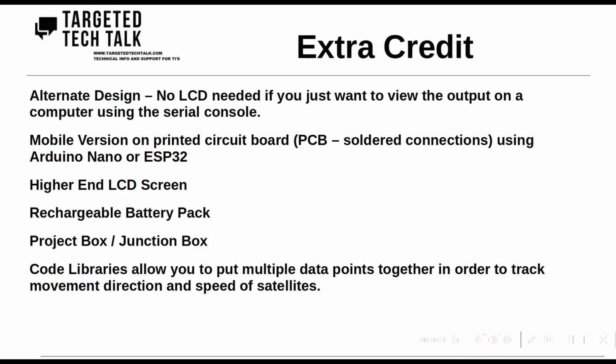If you were looking at a portable version of this, you would do this on a printed circuit board. I have an example of that on the next slide. So versus a breadboard where most of the components are plugged in, the one bit of soldering I did for this project was the 4 header pins for the GPS chip. I did need to solder the 4 header pins on so that it worked with the board. It just comes with the empty sockets, so you need header pins to work with a standard chip like this or a breadboard. So if you're just doing the breadboard version, that's the only soldering involved, the 4 header pins.